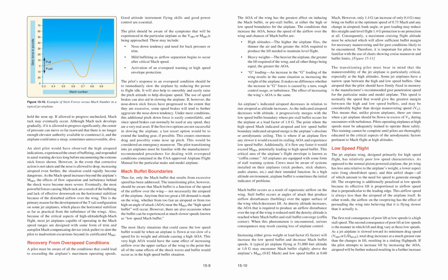If, however, the nose-down stick forces have progressed to the extent that they are excessive, some speed brakes will tend to further aggravate the nose-down tendency. Under most conditions, this additional pitch-down force is easily controllable, and since speed brakes can normally be used at any speed, they are a very real asset.